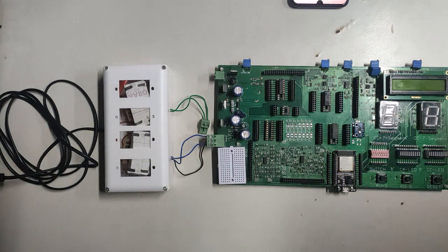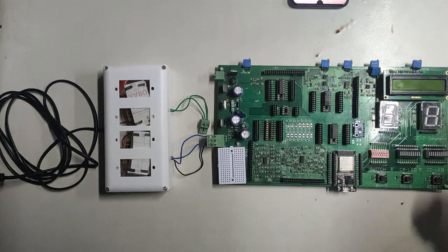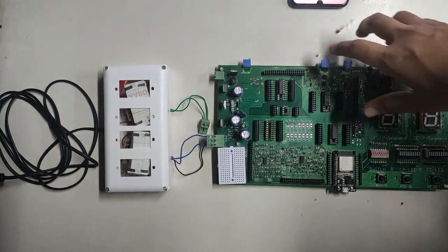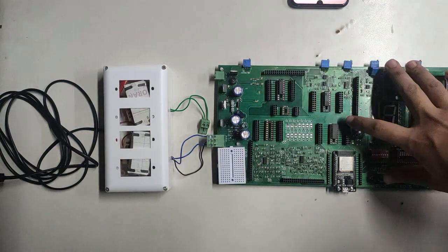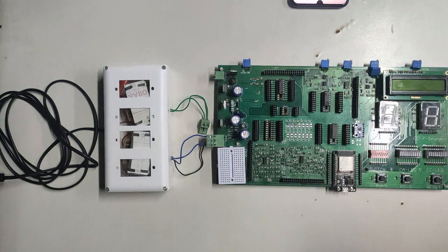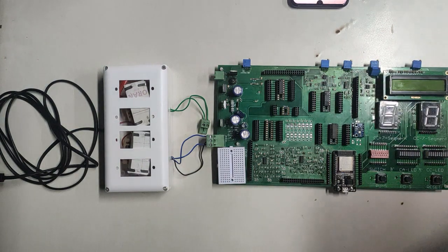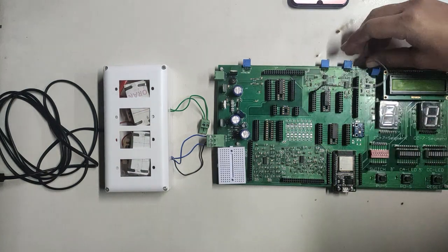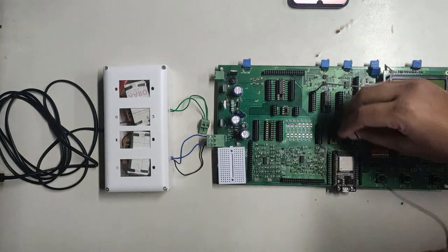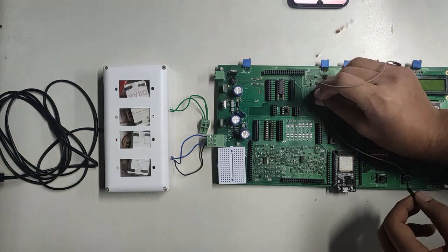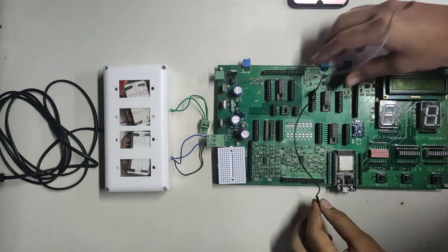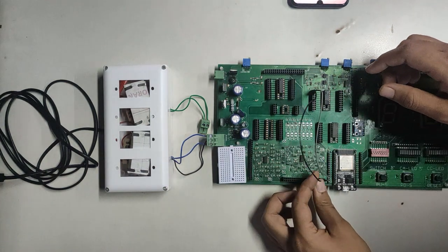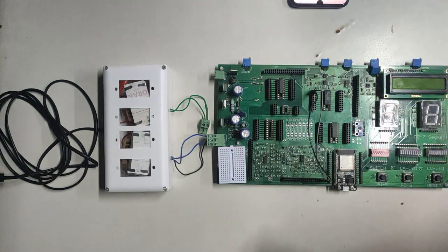Now let us start the implementation of half subtractor. For that we will require 3 ICs, which are IC7486, IC7404 and IC7408. The half subtractor has two inputs, which are input A and input B. Before making all the connections, we have to first connect the VCC and ground for each IC.